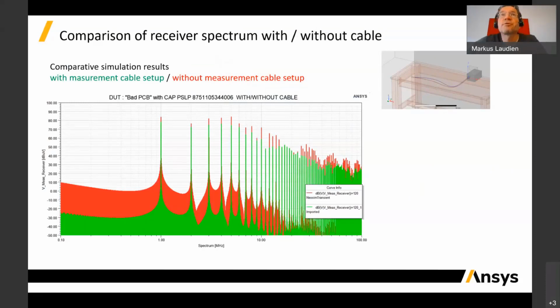And this is what I want to show you here, the comparison of the setup with cable and without the measurement cable. This is what I mean by adding these 2 microhenry, or respectively the inserted S parameters, which you have seen. There is a quite strong deviation depending on what you're doing. And you can be sure if you put the measurement lines closer to each other, this means the inductance gets reduced a lot, then the deviations will not be as strong as can be seen here.